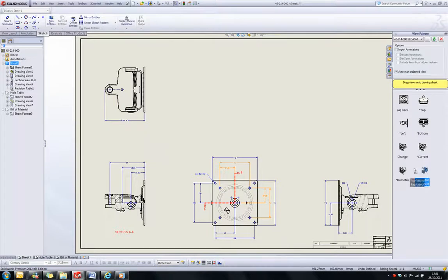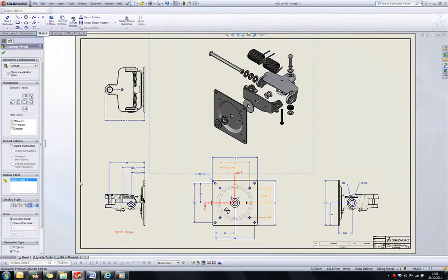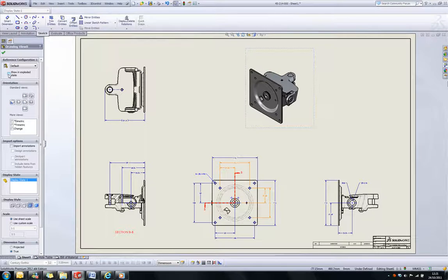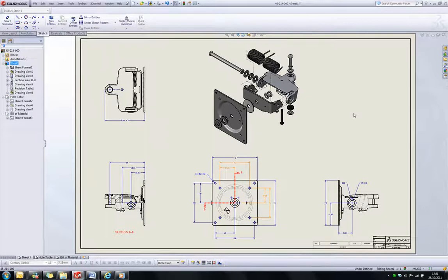Exploded views are also quicker and easier to make. If the assembly contains an exploded view, SolidWorks now automatically generates an isometric exploded view in the view palette. Any view that has an assembly with an exploded view state can now be quickly changed by toggling the option. No longer do users need to go into the view properties to make these changes.